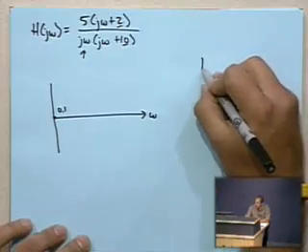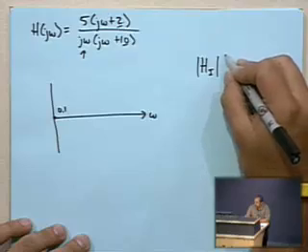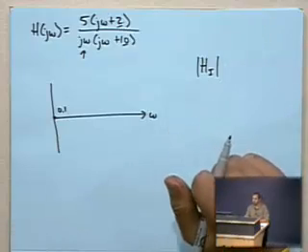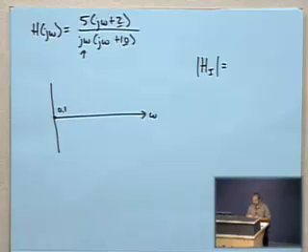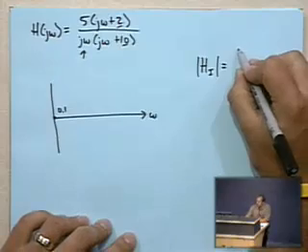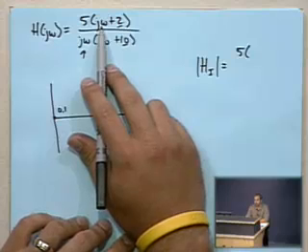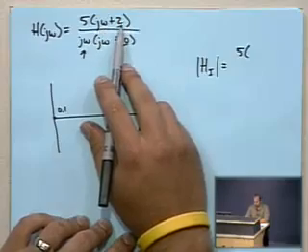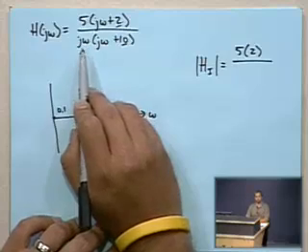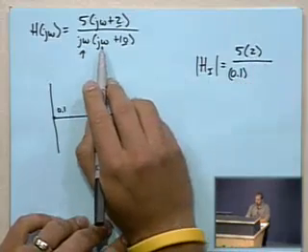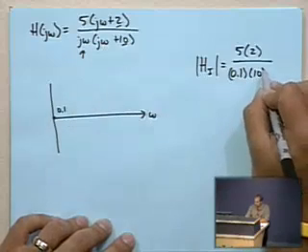And so our initial value, let's call it h sub I, we're going to evaluate at the frequency 0.1. And the way to do that, this works, and I'm not sure that I can give you a good explanation why necessarily. Say 5, apparently this j omega term of j times 0.1 is small enough that we're not going to worry about that compared to the 2 part, and so we're just going to say 2. This one, the 0.1 is significant, so we'll say 0.1. And then again, in this term, the pole, or the j omega part, kind of disappears, and so you just have 10.